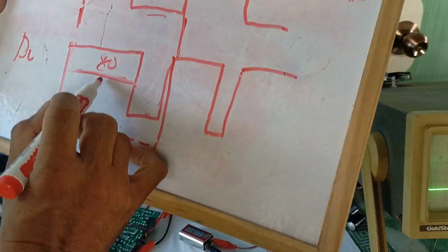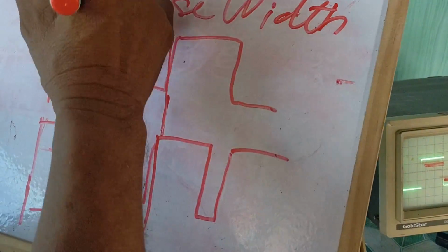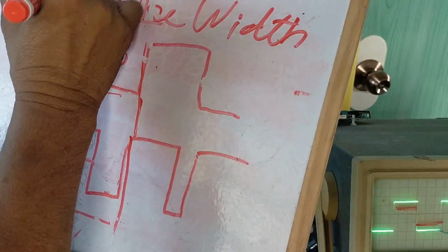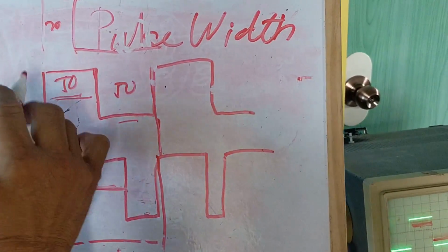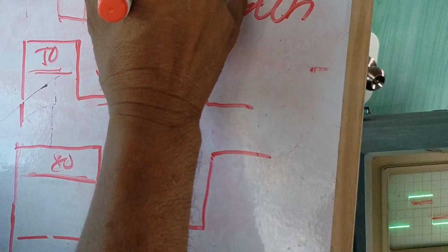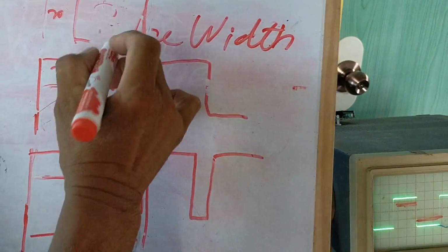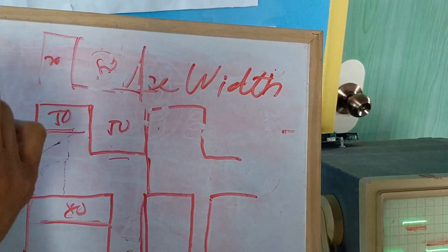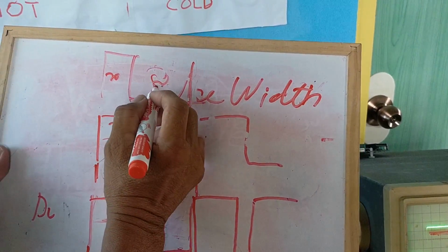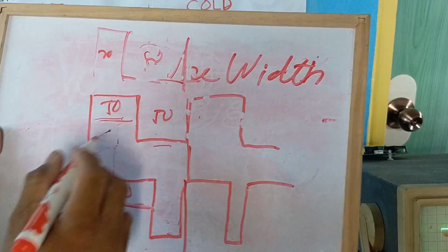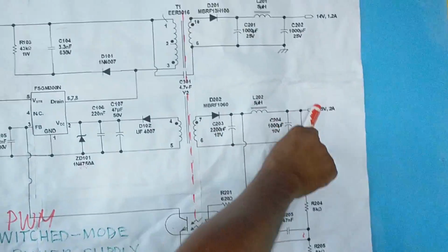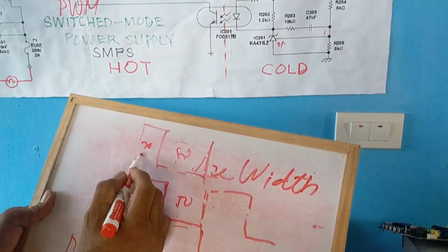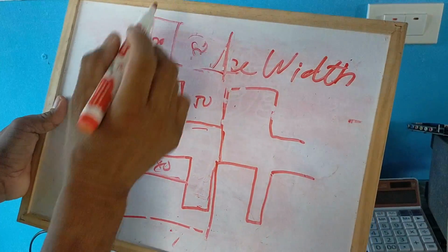So instead of 80%, we will make it a 20% duty cycle, turning on the transistor, and 80% for the rest. So the transistor should rest, or be off, 80% because there was an increase of voltage at the output. So the pulse width now, wherein the operation of the transistor is only 20%.